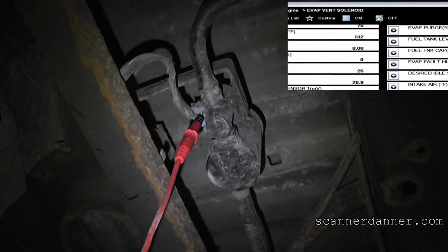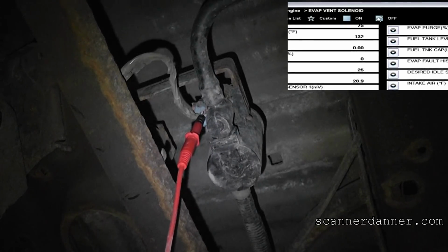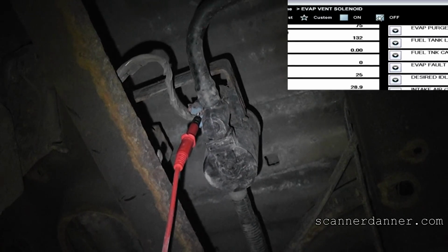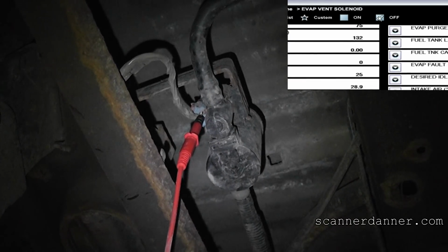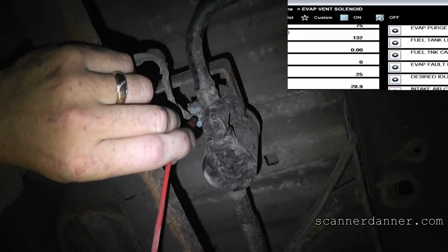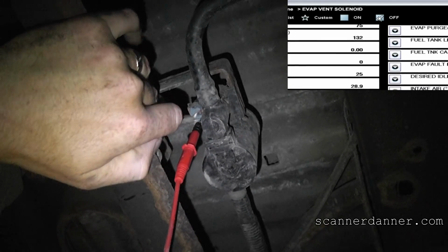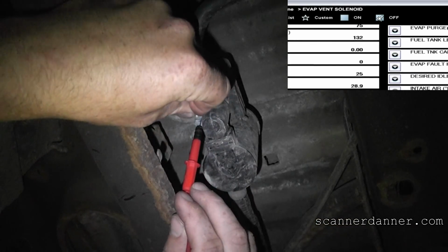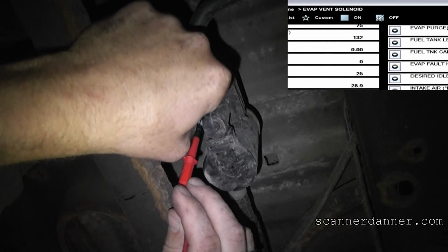I'm going to show you another method. Can someone hand me, I don't know if I can show you the test light version. I'm going to have to rig it somehow. All right, so for this part, I need to use a test light to battery positive, and I need to be careful with what I'm doing. Remember my whole double T-pin thing? Never double T-pin an output? You guys remember that discussion? Okay, well, I'm doing what I told you not to. I am ensuring that this does not touch. It's very important that it doesn't touch the other side.